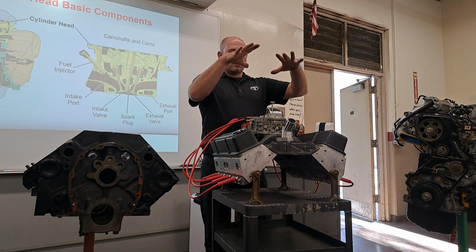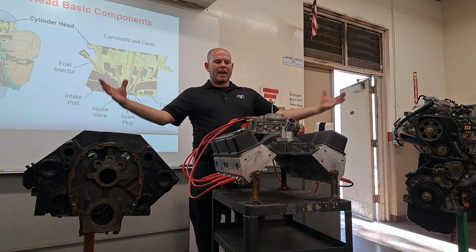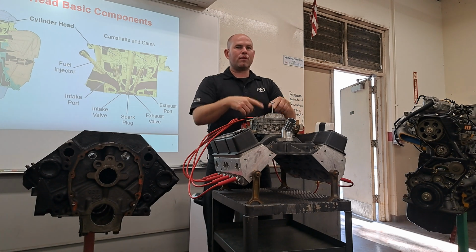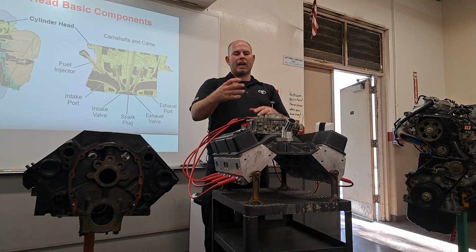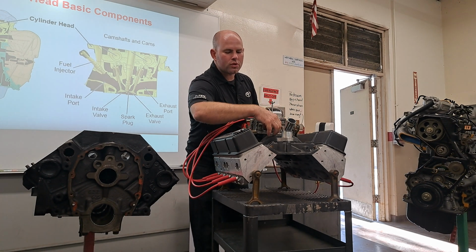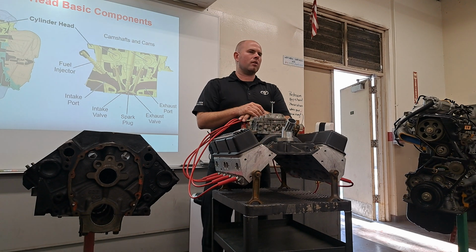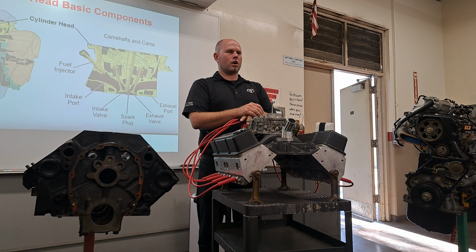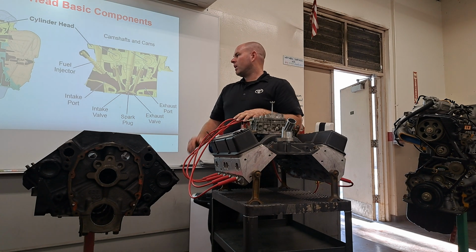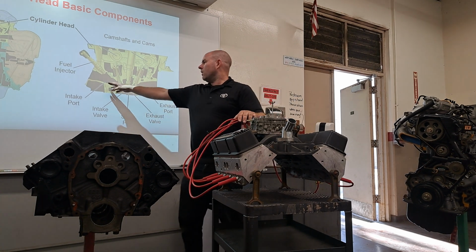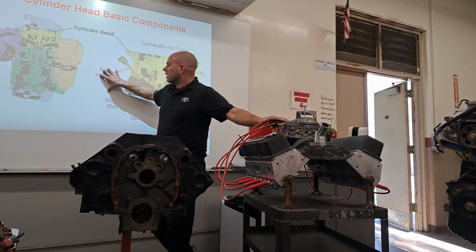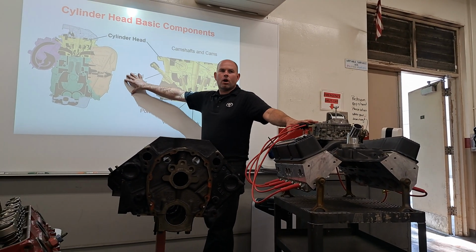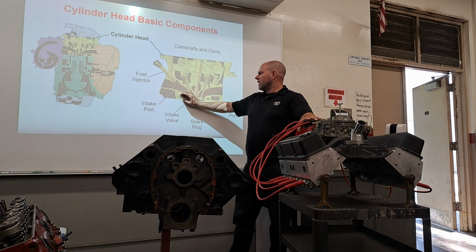But this was different, right? Air went in the air cleaner, and then right here, fuel was mixed. So air and fuel were going through this intake manifold together already. Make sense? This is not fuel injected at all. This was a carburetor. Now, when we went fuel injected, where the plenum would be, that would be all dry, and then just at the last second, it would get the fuel.